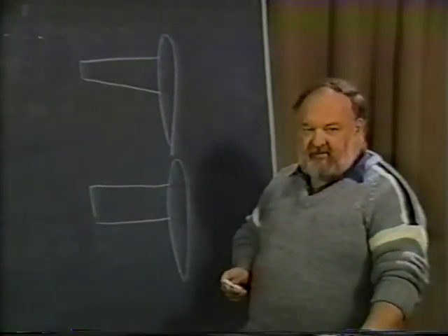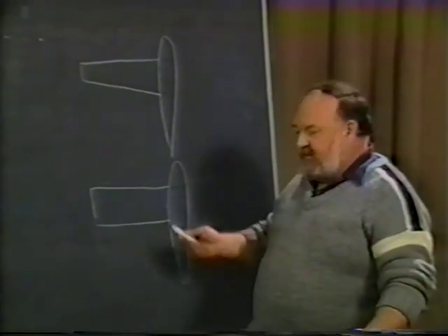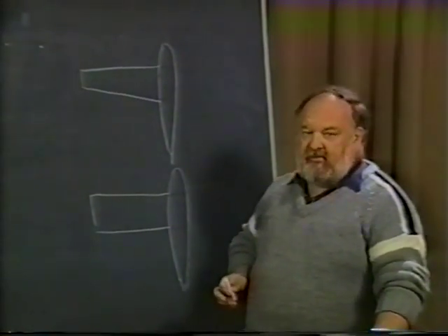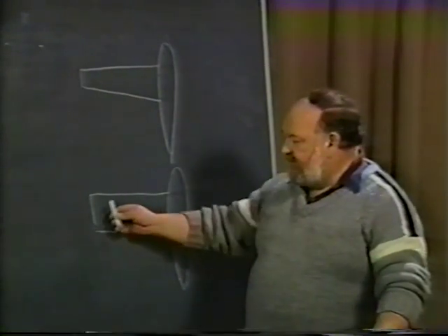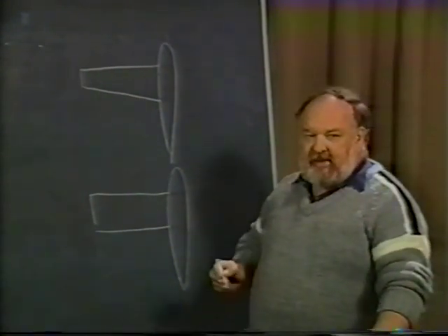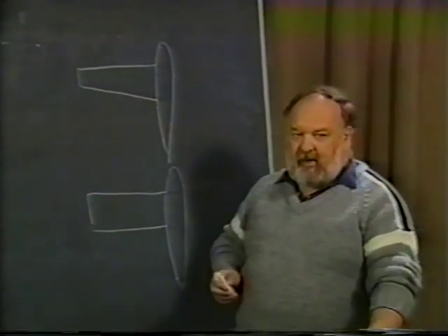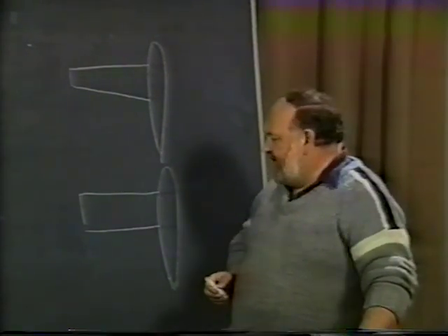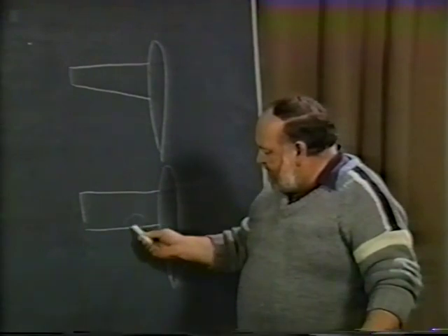The advantages are very definitely better in the fact that the Reynolds number at the tip now remains the equivalent of what the Reynolds number is at the root. So one thing you know right off the bat is, without any twist in this wing or anything else, that the stall pattern of the particular wing itself will be essentially the same throughout. Now, what are the things we're really going to be looking for? Why is stall pattern so important, and what are the main objectives? Well, the ideal thing would be to have a stall pattern begin right in this region here.